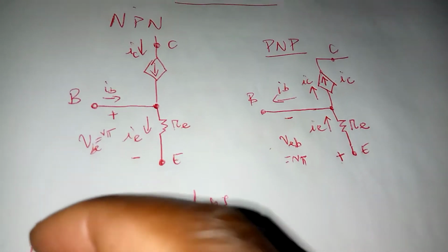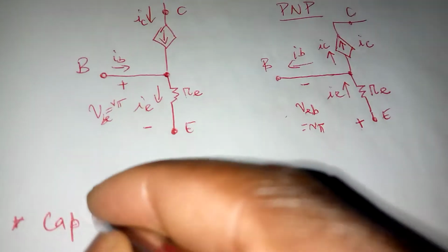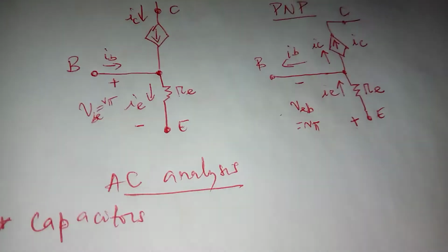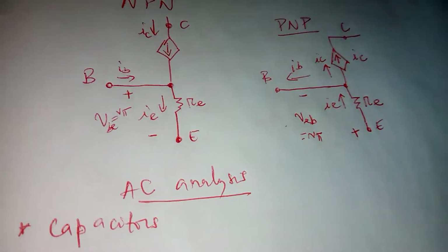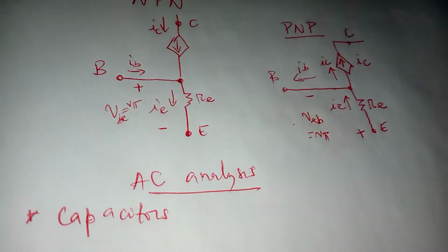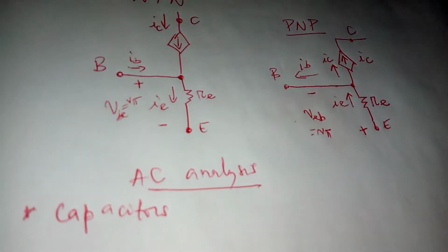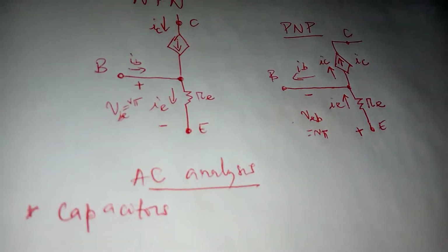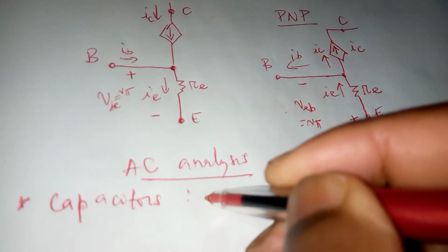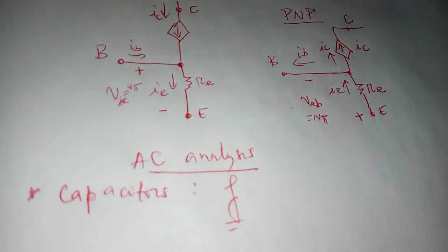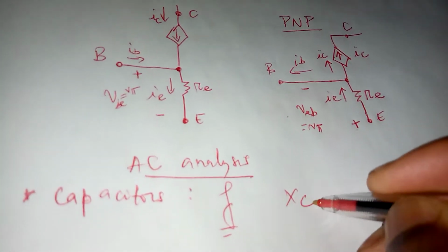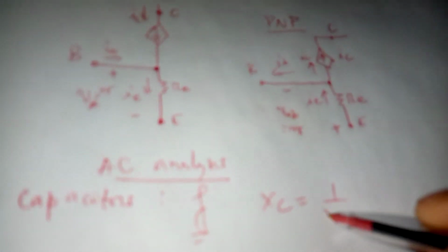But what about capacitors? This is the beginning of the definition of some rules that define how you start AC analysis. Given your circuit, what does it become when you're doing AC analysis? So capacitors. Now that we're in AC, operating at a certain frequency, they will have a certain level of reactance, which will be 1 over 2 pi f C. And for simplicity's sake, in Electronics 2, we will consider them like short circuits.